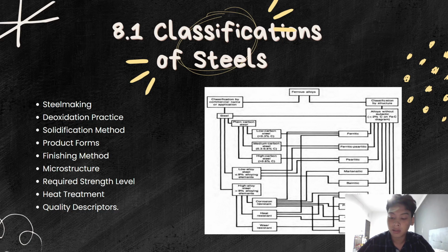Another category of steel based on strength is a group called ultra-high strength steels. These are commercial structural steels capable of a minimum yield strength of 1,380 MPa or 200 ksi. The three types of ultra-high strength steel are medium carbon low alloy steels, medium alloy air hardening steels, and high alloy hardened steels.